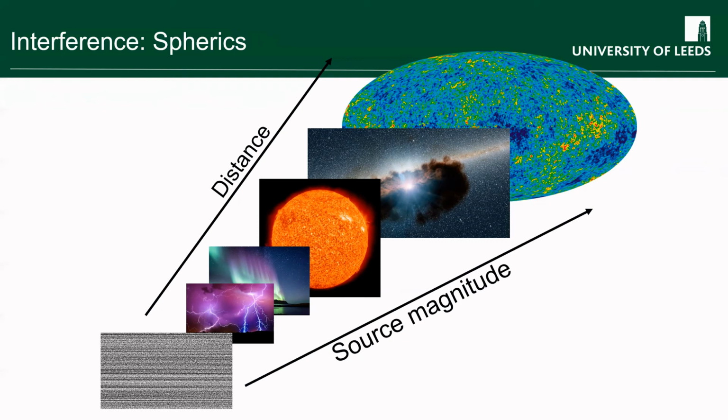And of course, the magnitude of the interference source will vary, as will the distance at which it is away from you. Locally, you've got some interference sources from things we're talking about, so other equipment in your lab, people doing experiments in the next door lab. And then we'd already mentioned the effect of atmospheric interference in terms of things like thunderstorms and lightning flashes.